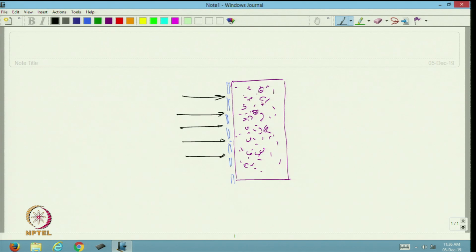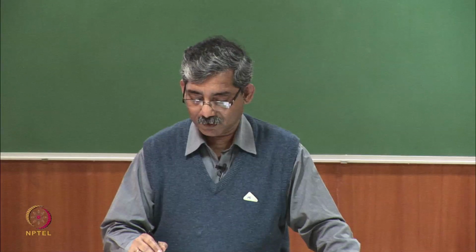The problem is that if we use a pore size of very small dimension, or try to block the pores to arrest the smaller soil particles, then it is a problem, because we have to allow the water to flow through so that the structure remains dry, but at the same time we should not allow the soil loss. So, this is a contradictory requirement.